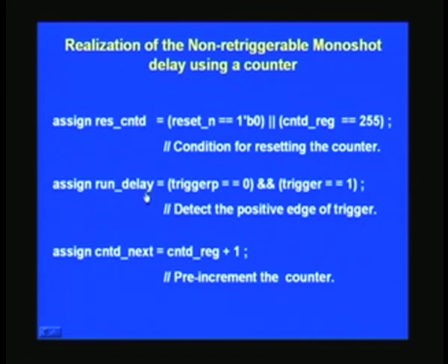And this one we have noticed that input is trigger, and we want to sense the rising edge of the trigger as such. How do we sense? One way is to put an always at positive edge clock, and there you can't have more number of clocks. Maybe in any system you need to restrict it to say 2 or 3 clocks, and don't cross that number. So what do we do if you have so many other signals which also need to be sensed at the rising edge, or for that matter falling edge? What you can do is you can have another signal which will store the previous value. So every time the clock strikes, the current value you can push into another flip flop and then store it and use that one in the next clock. So you will know what is available in the previous clock, that status here. So by ANDing this one, say for example previous value is 0 and present value is 1, naturally you can sense that it has a rising edge as far as this signal is concerned.